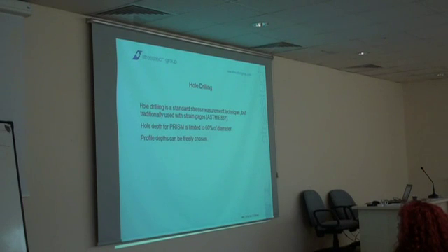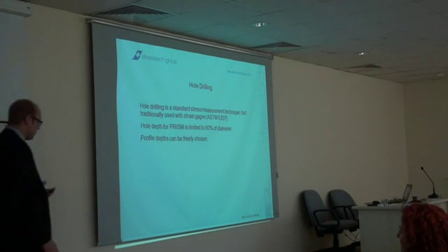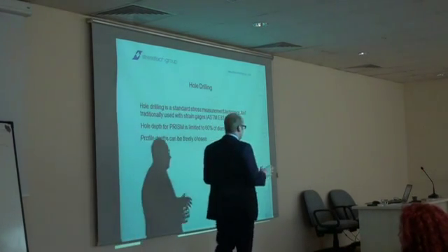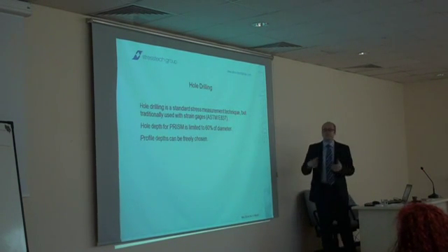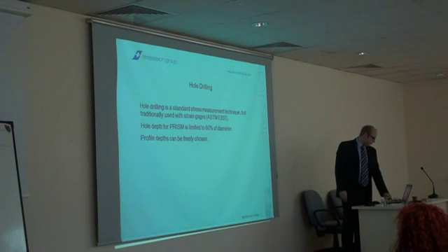And if we electropolish 25 microns away, we have the same depth here. But again, when we make a measurement with X-ray, it's the average value from the next 5 microns. So if you have a steep stress gradient close to your surface, you will get different values from the sample surface. But in most cases it's quite close, and typically after 15 or 25 microns, the results are quite close with both techniques.